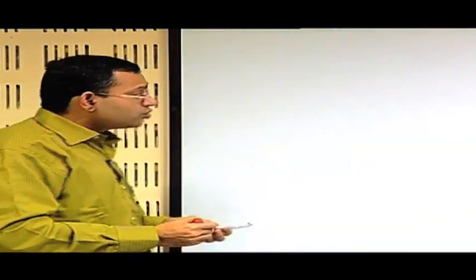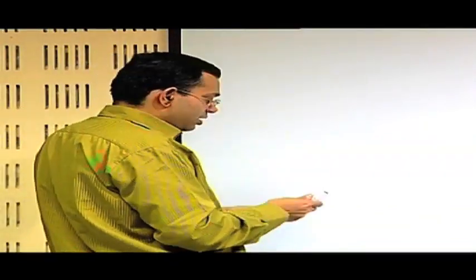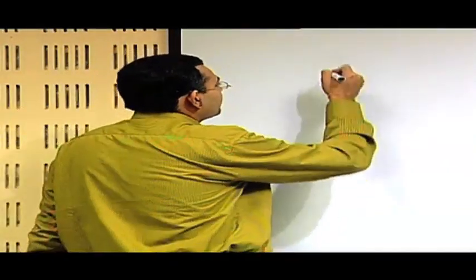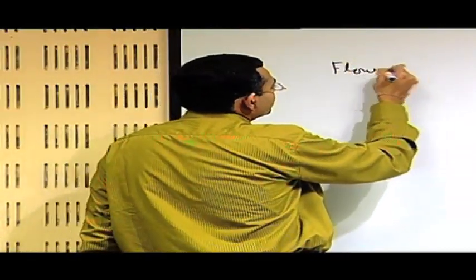More or less it will not be very inaccurate till there is boundary layer separation, but in reality there is boundary layer separation. Therefore in reality whatever pressure distribution is predicted by the potential flow does not work. It works approximately well till the point of separation or very close to it, but not far away from that. So first of all we will consider the case of flow past aerofoil sections.